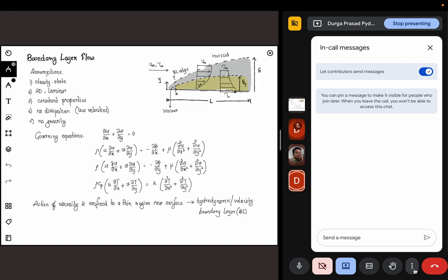So these are the classic equations where we have the continuity equation, x momentum, y momentum, and then the energy equation that we derived just now. Here in this boundary layer, when the velocities are very small, the viscous effects are negligible. So we don't have the mu phi term. And there are no chemical reactions, radiation or anything of that sort here. So the Q triple prime, the heat generation, is also 0. So we just have the conduction term and the advection term. Now we are making further assumptions, saying that we'll reach a steady state. So there is no transient term in any of these equations.